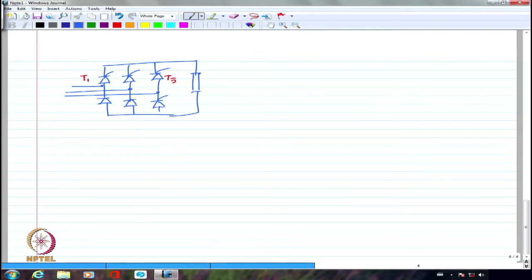When I am firing T1, this is A, this is B, this is C, this happens to be a short circuit. Already this is conducting, right? So, whatever is this C, that C comes here. I am going by the same logic, whatever we talked earlier. So, for me to fire T1, VAC has to be positive. If VAC is not positive, I will not be able to fire T1. And VAC zero crossing is alpha equal to 0.